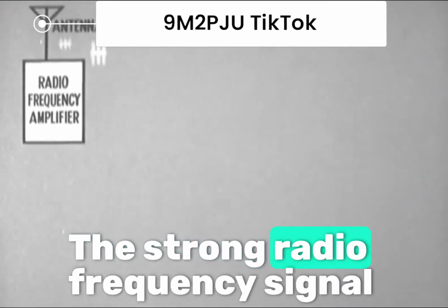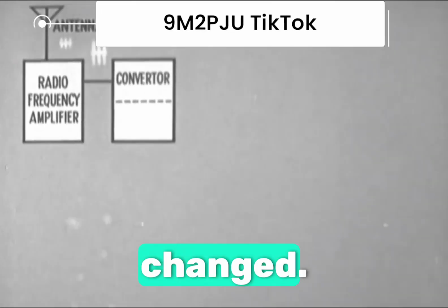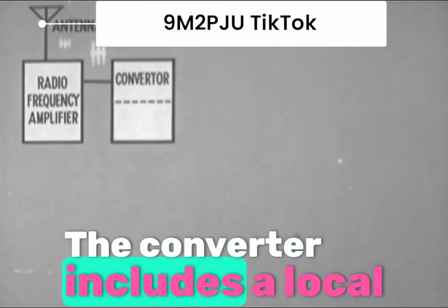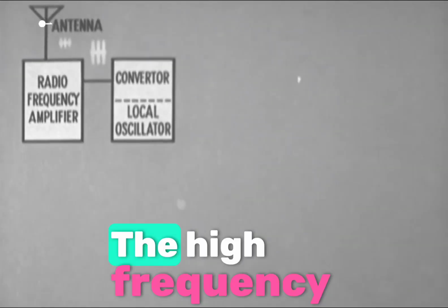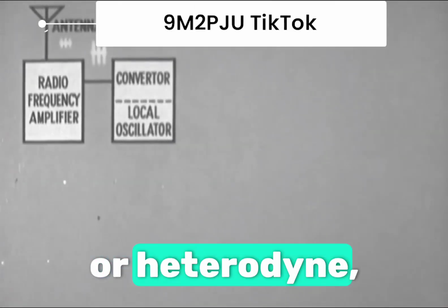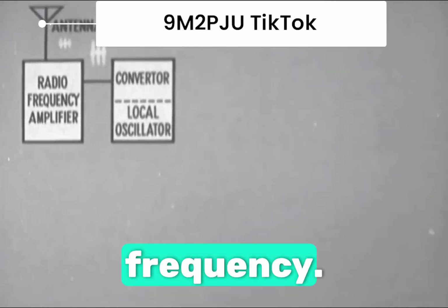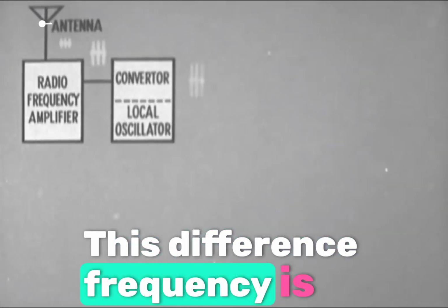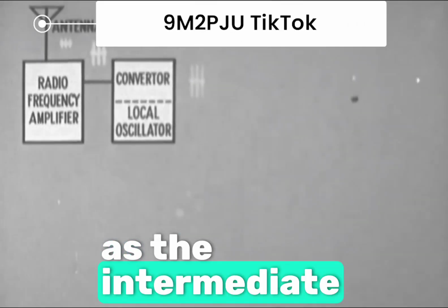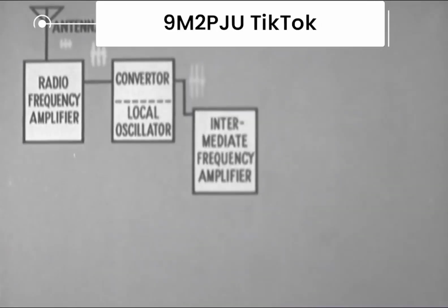The strong radio frequency signal is fed to a converter, where the frequency is changed. The converter includes a local oscillator. The high-frequency output of this oscillator is made to mix or heterodyne with the incoming signal to produce a difference frequency. This difference frequency is known as the intermediate frequency and is fed to the IF amplifier.